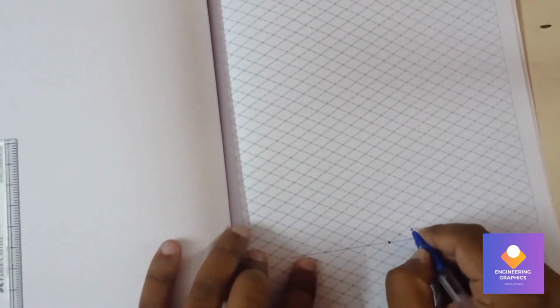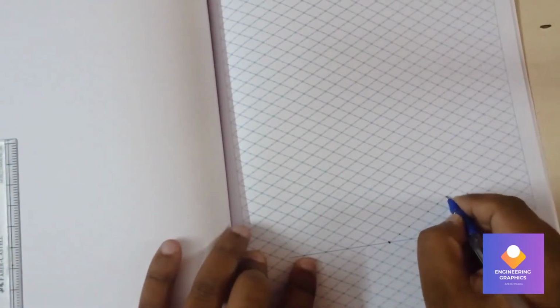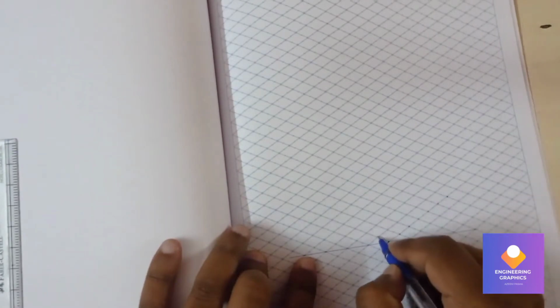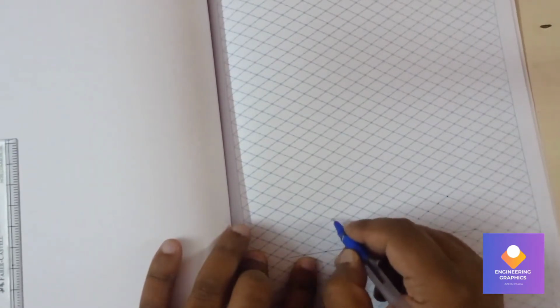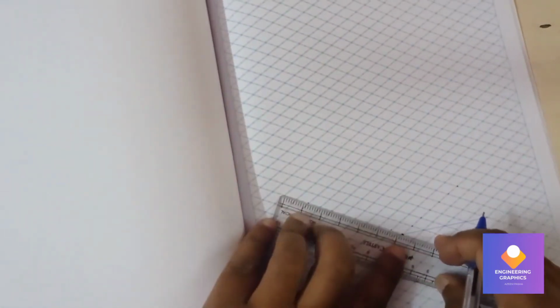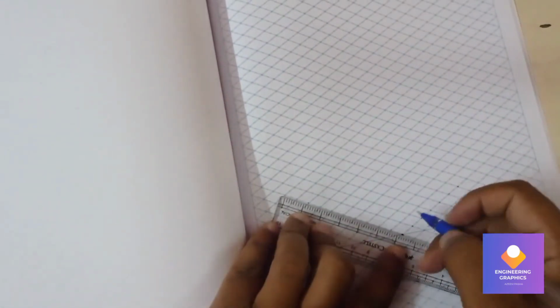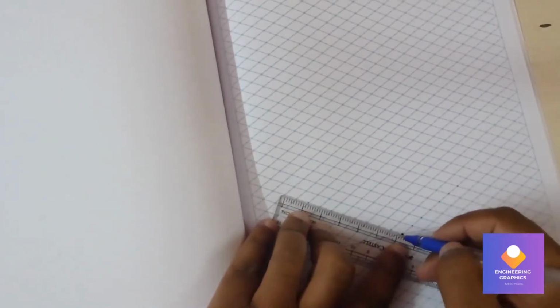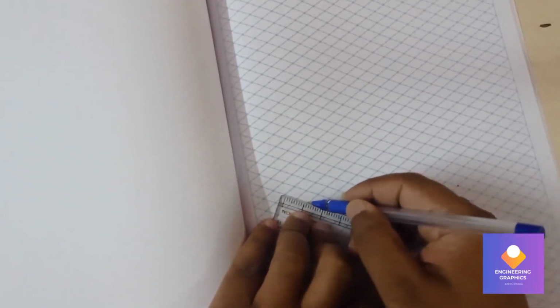So first you draw a reference line. You take one reference point. From this reference point you consider the boxes here. 60 means 6 boxes, and 80 means 8 boxes. 1 2 3 4 5 6 7 8. Now we can construct it. 1 2 3 4, you can recheck again. So now we have to construct the rectangular box here, the rectangle. Then after that we will be giving a height of 20.